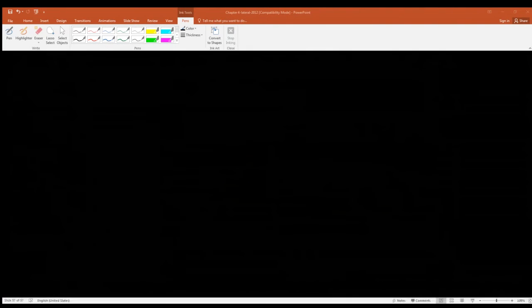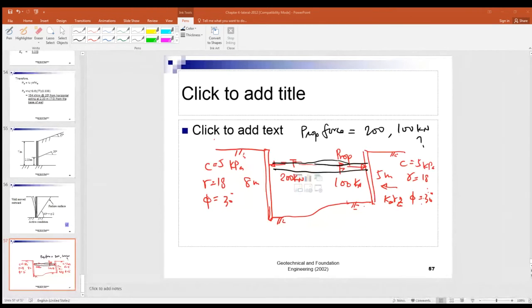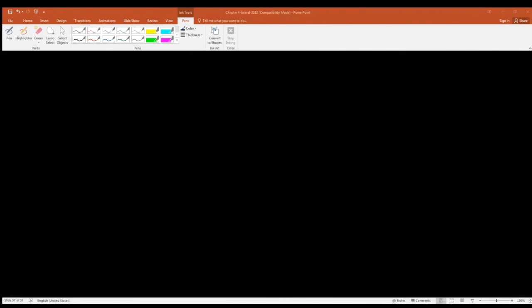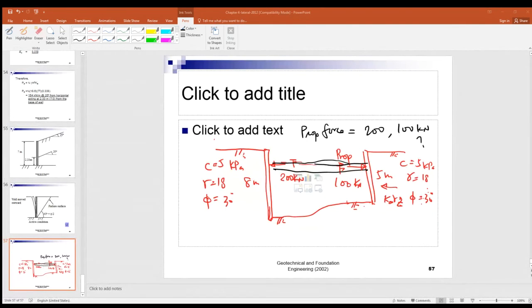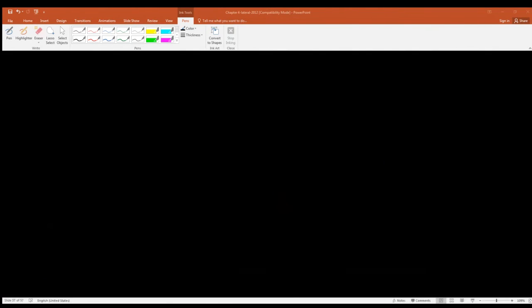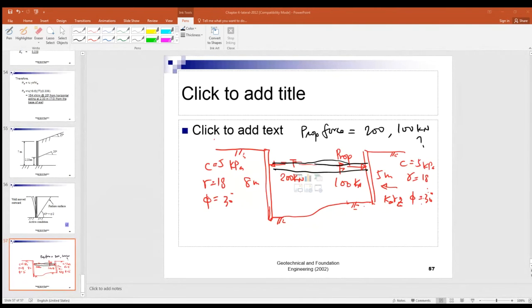And the potential failure of the soil slope may be caused by several means, right? Whether the slope is too steep, or you may have a groundwater problem. The groundwater inside the slope may try to come out and push the soil downwards. So groundwater is the chief enemy, right, behind any slope failure.